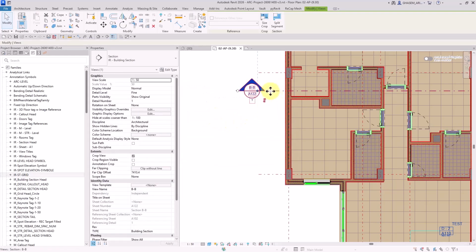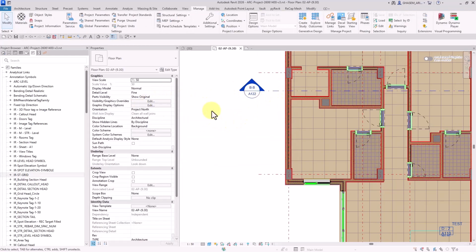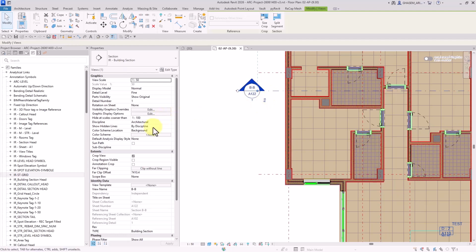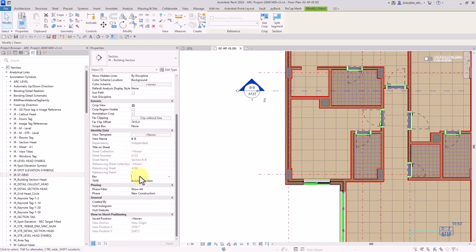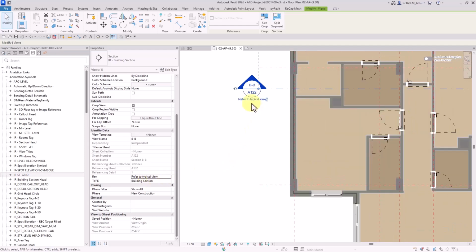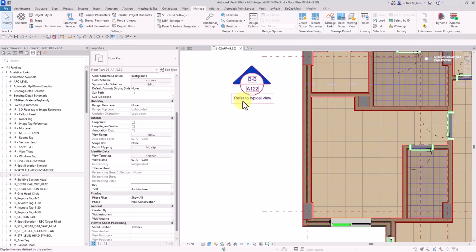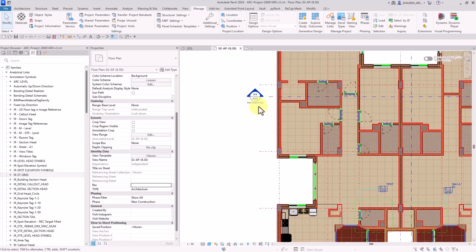Now again, if I go ahead and select this in the Properties tab, we would find REV. Now we can specify a value for this. I'm just going to copy paste something here. And immediately afterwards, it would be displayed in the viewport. Basically, there's no limitation here, guys. You can go with any value that you want. This is a very interesting item, honestly. Could be quite helpful in documentation.